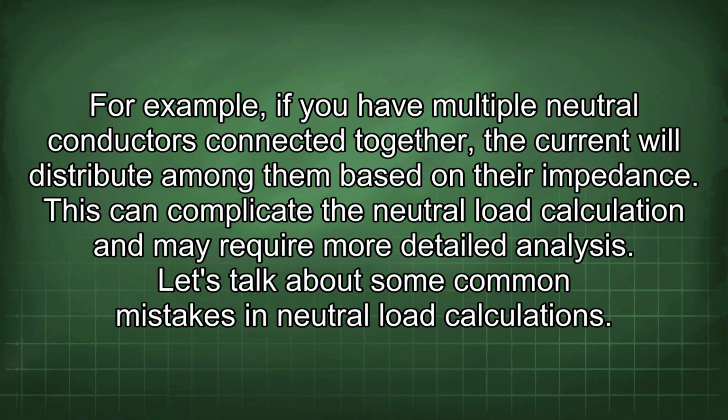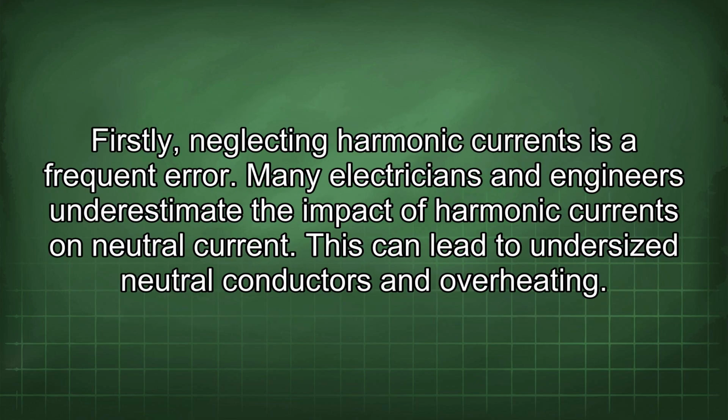Let's talk about some common mistakes in neutral load calculations. Firstly, neglecting harmonic currents is a frequent error. Many electricians and engineers underestimate the impact of harmonic currents on neutral current. This can lead to undersized neutral conductors and overheating.